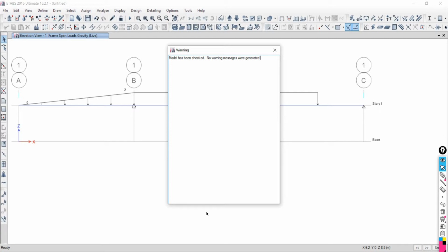Otherwise, if you need to delete anything after assignment, such as fixing a modeling error, the load will also be removed along with your element. That will be the problem. That's why first correct your model, then assign the load. But if you are working at expert level, you can do anything, and check your model after the assignment also.